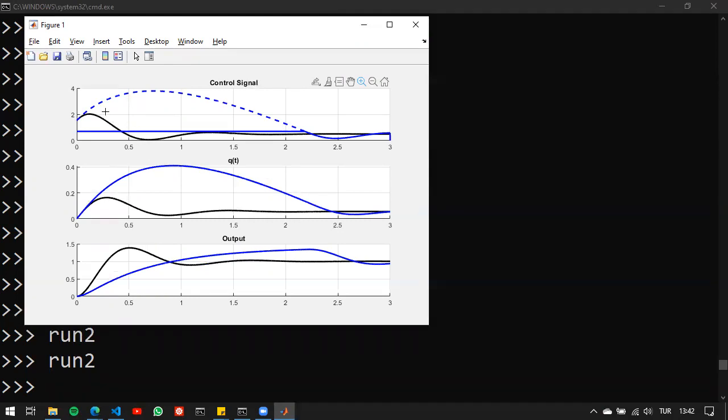So what we try to do here is behave like a P-type controller during saturation, and then we'll activate the integrator between the limits. If it's between the limits, then we'll again turn on the integrator and apply PI control. So it seems like we don't really have to use a PI controller during the saturation because we cannot even use any controller, because we are just applying the limit. This is not a controller, this is the limit.